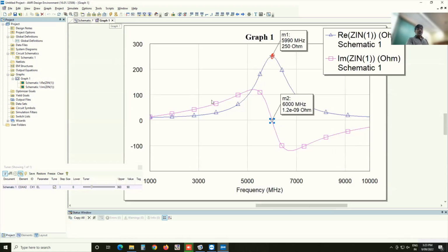But by changing the length or frequency, you can create both real and imaginary parts at that particular point. And again, this is not so surprising. It's because now the reflected waves will come at various angles, and then that will determine what is the ratio of voltage to current at any particular point, and that will automatically give rise to real and imaginary parts.